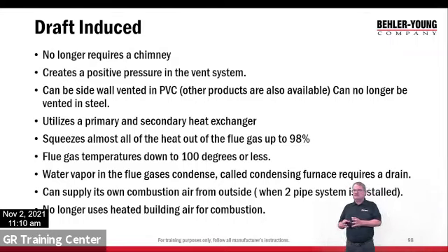We've had to go to specific plastic for certain boilers that require a specific plastic venting. The PVC may go away because I know there's some talks about that, but currently 90% furnaces, we still use PVC pipe. Why? Because the flue gases are so cold that we're condensing and they're waterproof.